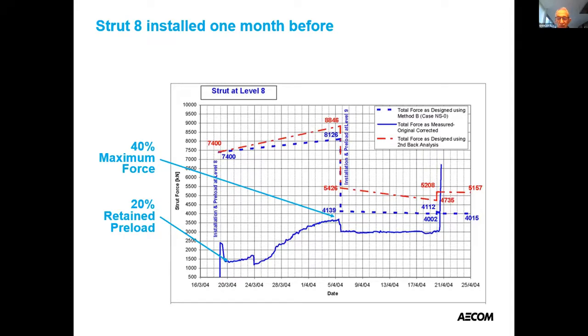Although you can notice that on the day of the collapse, the arrow doesn't show very well, it's lost on the white background, that at the end of the day, on the 20th, going towards the 21st, as the load in strut level 9 in the previous plot was dropping, it was transferring its load into this connection, which went up so far and then collapsed.